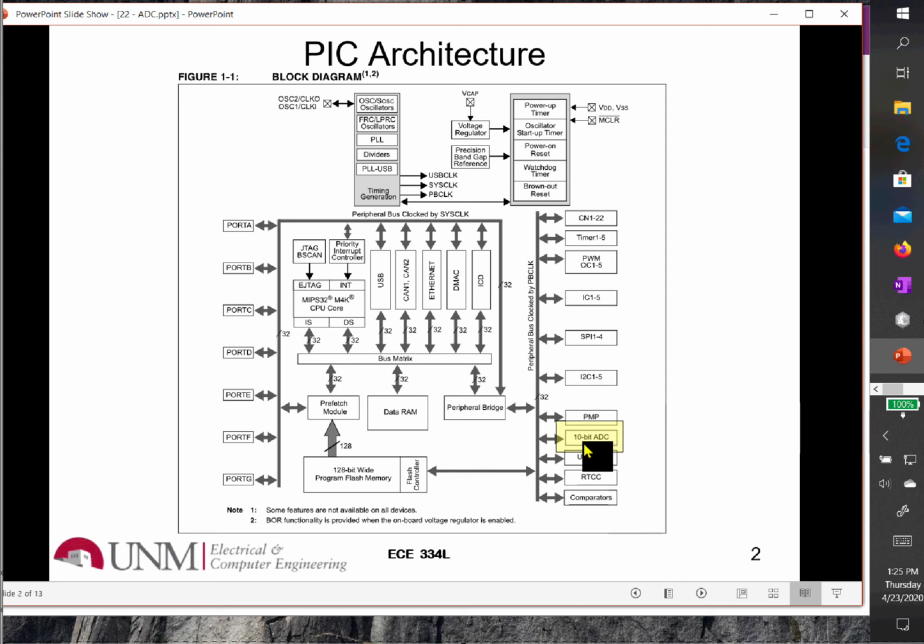In our implementation, we have a successive approximation conversion. So we see it's going to take a certain number of bit times. It's got to take at least 10 clock cycles to do this conversion because we have 10 bits. And we'll see that actually it's going to take us 12 clock cycles to do a single conversion. We also have to worry about how fast our analog to digital converter is, and at what rate it can do those conversions. Do I have to slow down the peripheral bus or not?